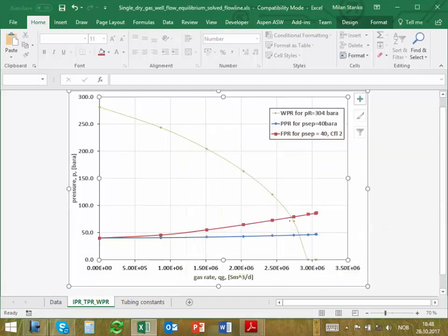Okay, you see the two? Did you get the same? Still working? Okay, but you see that there is a difference, and that pipe is significantly smaller. And now you have to make a decision based on how much rate you're going to get over time, if it really pays off to buy this line instead of this line. Okay, this one is very big, probably has almost no pressure drop on that distance.